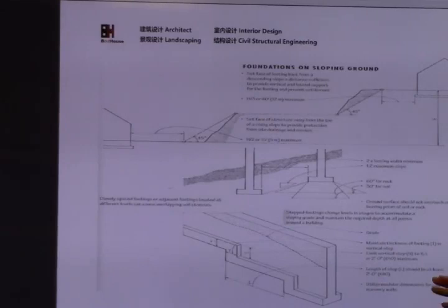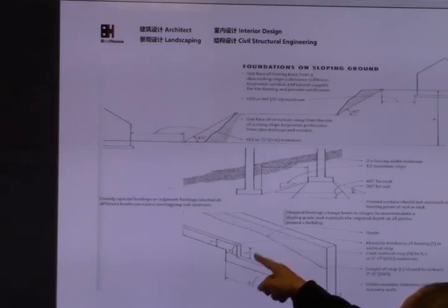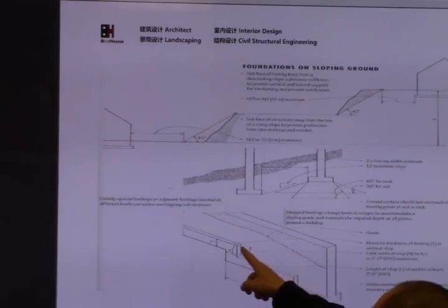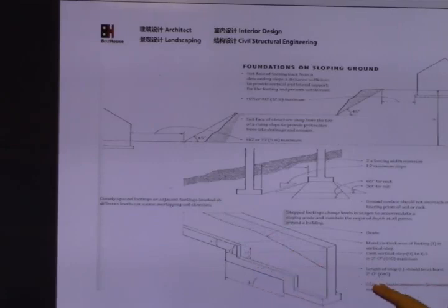If your site is sloped, then for the footing we need the step footing. For example, if your basement is on a slope, but we need the basement to have a window, right? If the concrete wall is higher, flush with the top, we cannot have the window here. So we step the footing. Yeah, this is very common for a slope site.